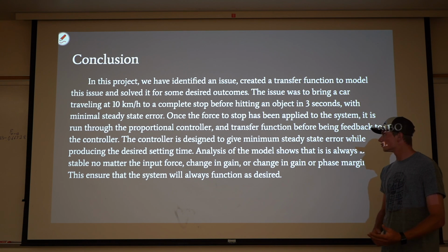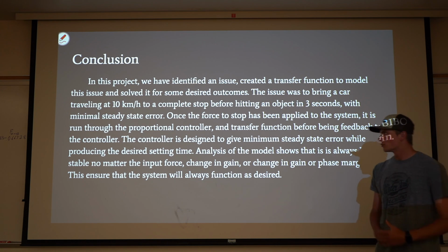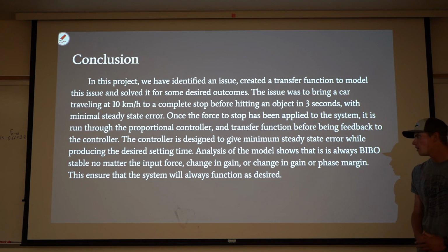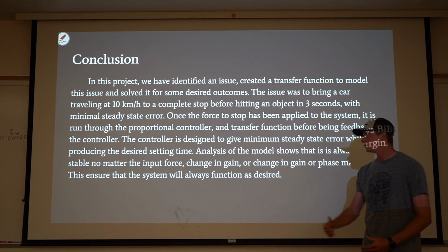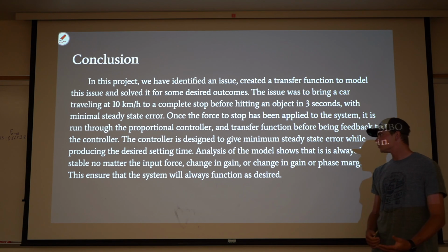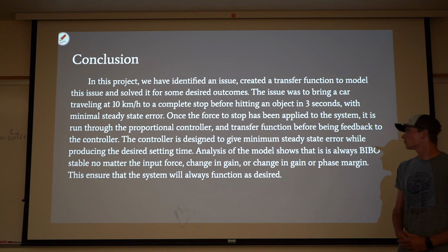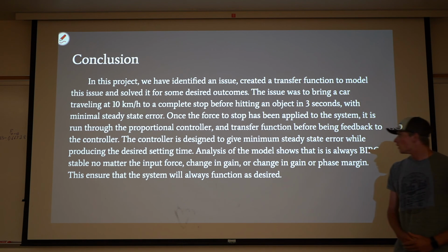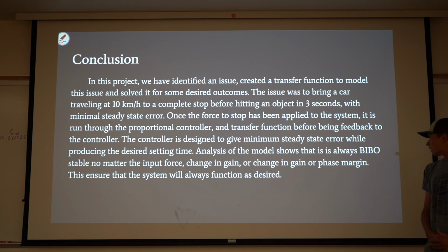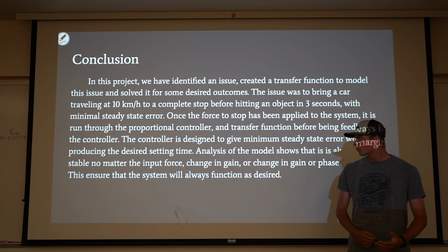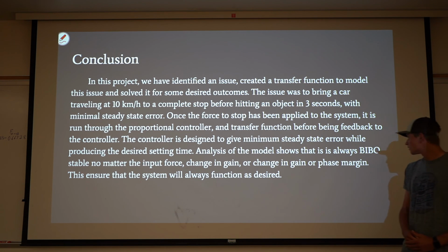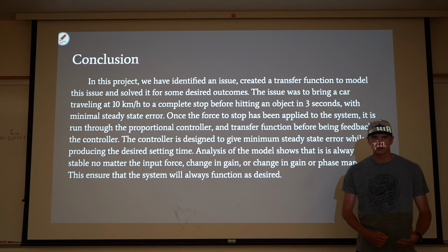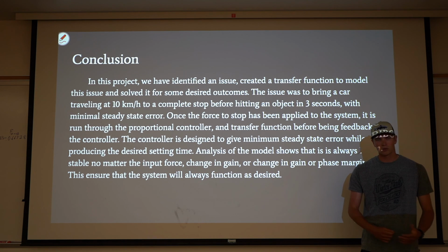Once the force to stop has been applied to the system, it is run through the proportional controller and the transfer function before being fed back into the controller. And this will then eventually take the system back down to 0. So the controller we use is designed to give a minimum steady state error while also producing the desired settling time of 3 seconds. An analysis of the model shows that it is always BIBO stable, no matter the input force, change in gain, or change in gain or phase margin. So this ensures that the function will work properly every single time, no matter what is inputted or whatever else changes.